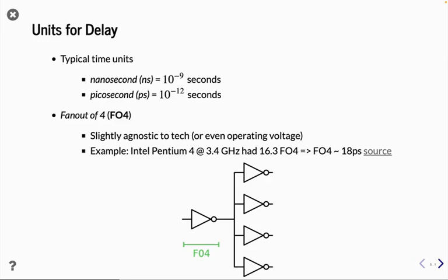So when you talk to people in architecture, especially in industry, who are doing hardcore physical design optimization, to get a sense for how aggressively to push the clock, rather than talking about frequency, they talk about FO4. Okay, this is a design we're trying to shoot for sub 20 FO4. That means you really have a carefully optimized pipeline. You're really going fast. For some research projects where we have a hard time reaching a high clock rate in FPGA, I shudder to figure out what the FO4 is. It's probably in the hundreds, right? We have a very long, complicated combinational logic path, and so it's a long delay path. And so that happens. So yeah, there's a little side here to see this FO4 metric. We haven't seen it before.